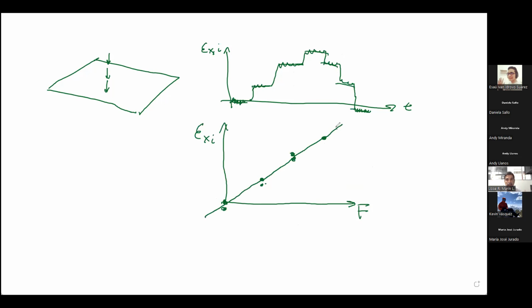Those are the results. What we can do now is set a straight line, a regression, like this. So this is going to be your experimental results. This is never exactly 0, but it's always a good idea to check if you came back to the original value. The original value was very close to 0. If you have a large value here, probably there are some problems in the test. So basically, you do not accept this value. What you have to do is check and try to find out what's wrong, correct the problem, and then do the test again.